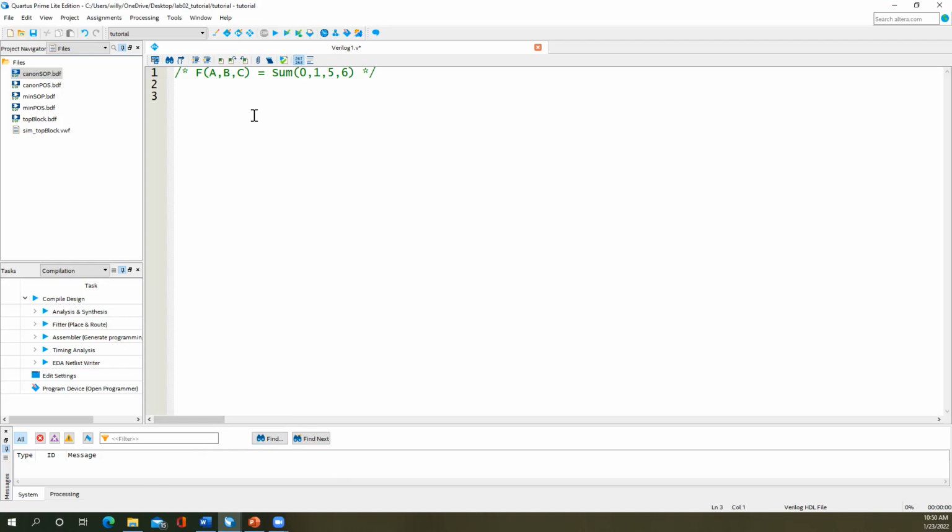All right, so whenever you write a Verilog module, you begin with a keyword module. All right, so you can see as I typed it, it was in black, and as soon as I hit the space key, this turned into blue. Here, using Quartus, or if you use some other text editor program that understands Verilog, so a file with a .v extension in a programming text editor that understands Verilog will then show your keywords in a different color. Here in Quartus, our keywords are going to show up in blue. And keywords means that this word has been defined by the language to have its own special meaning, and we should not use it when we create our own identifier names.